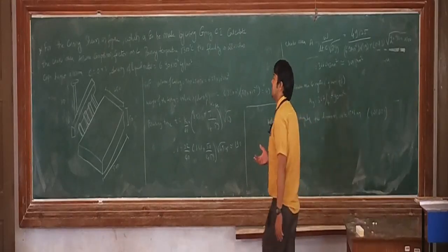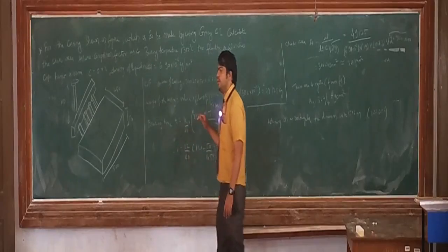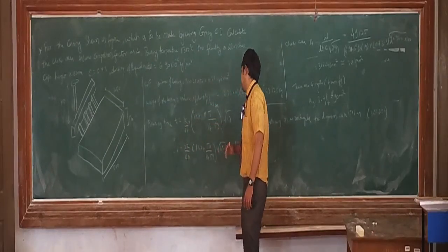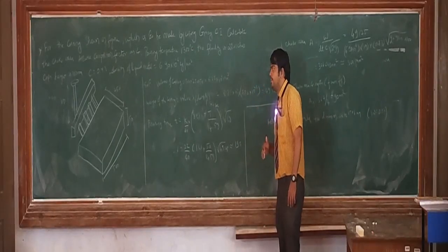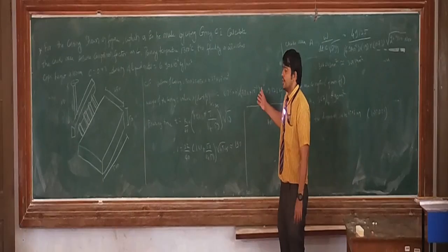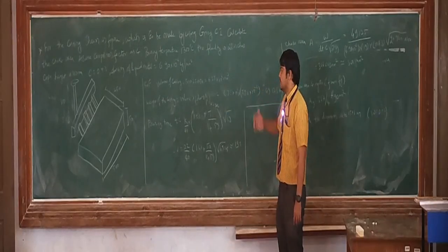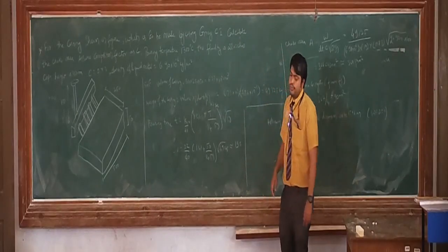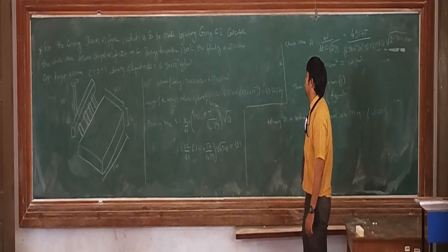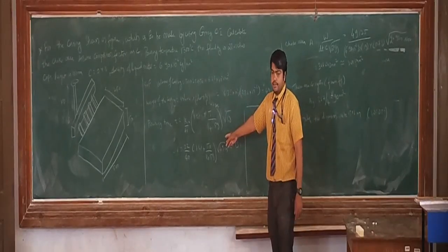As the metal in the casting is in the solid state, we are going to consider the solid metal density. So solid metal density is 7.86 times 10 raised to minus 6 kg per mm cube. Grams per centimeter cube is converted into kg per millimeter cube, so that is why we have this 10 to the power of minus 6. Once we do that, we get the weight of the casting as 49.125 kgs. This casting weight will be substituted in the pouring time formula.